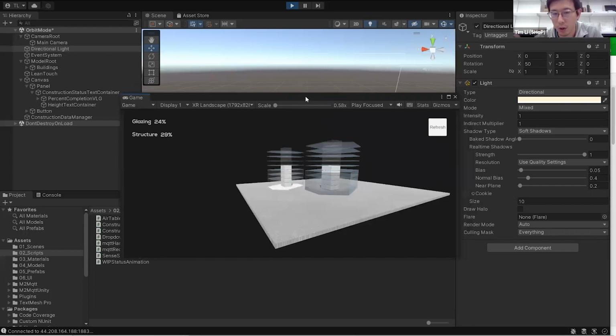And also what we forgot to mention is that polygon count, of course, is a big concern for real-time rendering. The other one is object count. So you do want to keep the number of objects down to a minimum if you can.